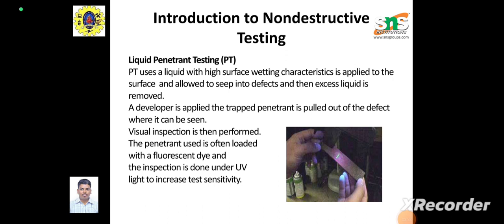It has certain advantages and certain disadvantages. Suppose we use it on a material sensitive to the liquid, such as corrosion-prone material. Then the selection of the solvent and the liquid becomes most difficult. We cannot use it for different types of industrial applications, because the liquid may react with the material and produce different kinds of solvent. Selection of solvent must be cost effective, otherwise we increase the process cost. So then we have to go for the next type of testing technique, which will be more useful.